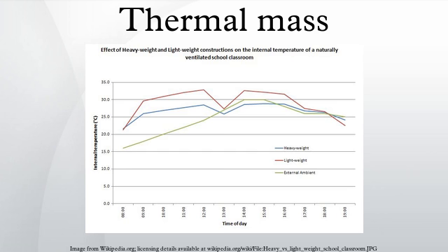Any form of thermal mass can be used. A concrete slab foundation either left exposed or covered with conductive materials, for example tiles, is one easy solution. Another novel method is to place the masonry facade of a timber-framed house on the inside. Thermal mass in this situation is best applied over a large area rather than in large volumes or thicknesses. 7.5 to 10 cm is often adequate.